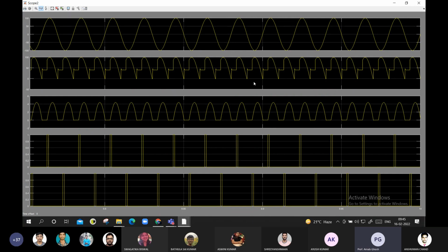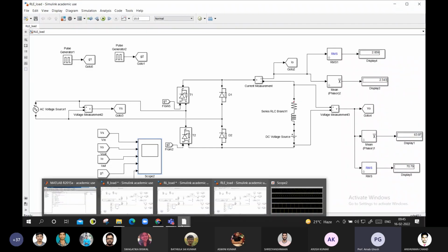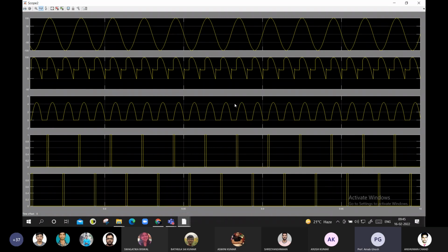Your output voltage is 40, then? Sir, for the first 40 degrees we get the E value, that is 40. After that, conduction starts. How much firing pulse do you have? Sir, it's 60 degree. And the maximum output voltage is coming how much? Sir, 100 volt is coming, the maximum peak value. Okay, so make the back EMF E value 95. Okay, sir.